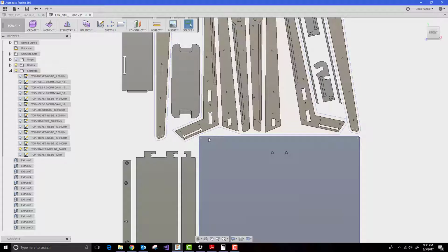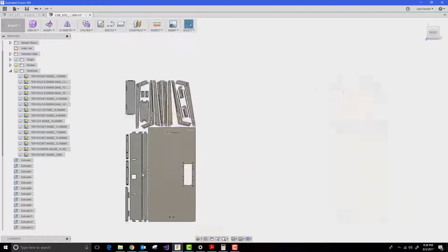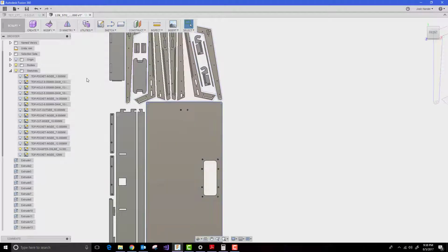And then here they want it to be 14 millimeters down because they're going to do a true chamfering off of that size. So that's what the chamfering step does. That's why we don't actually put it in the model, because if there's one thing I've learned, don't put chamfering in your models. Let the CAM chamfer for you. Just tell it the paths you want it to chamfer, and it will. Unless there's some reason you have a specific chamfering shape that you absolutely need in your model. The one thing I would add: hey, Opendesk, if you're watching this, have everybody add a chamfering angle that they want there. I think it's silly not to have it, so I would say that's a missing thing that needs to be there.